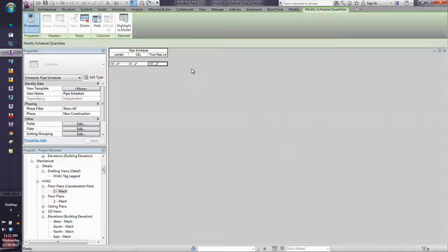Another thing that we did too is that you can drop using the load description and put your own circuit name parameter in. That's another way that you can do that. And you just make it an instance parameter so that you can assign it to each individual circuit, and then life is good. You can make it whatever name you want.